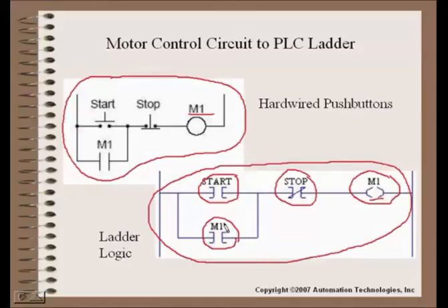Now, actually, I don't like to do this. This is not where we like to stop. We like to take this relay coil, take a contact that would come back from that relay coil, and then enter that into our PLC program. Therefore, we have a real-world understanding when we seal our circuit in. If this relay were to drop out for any reason in the field, then it would also drop our seal in the program.